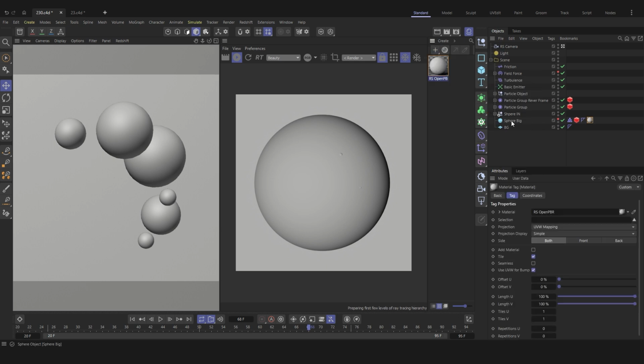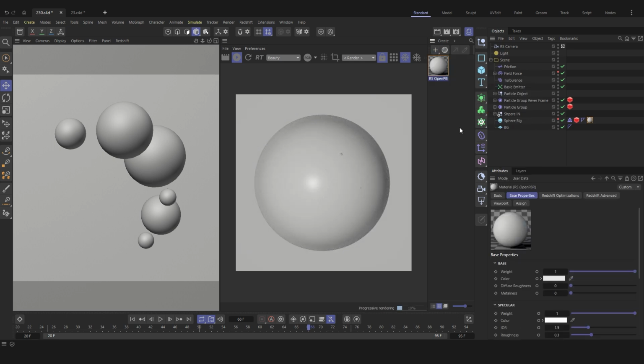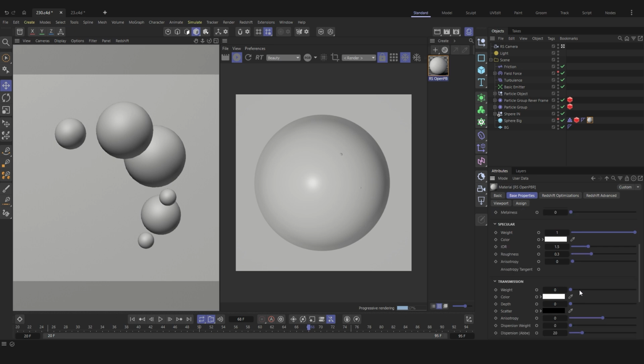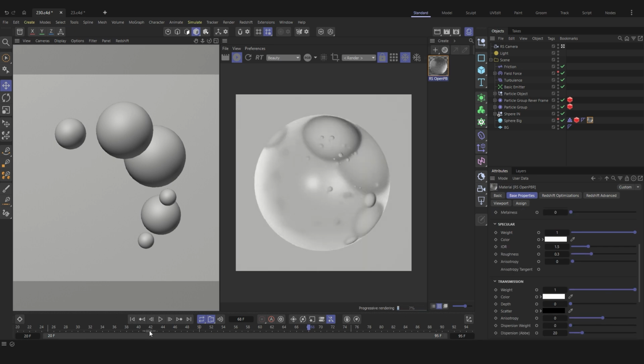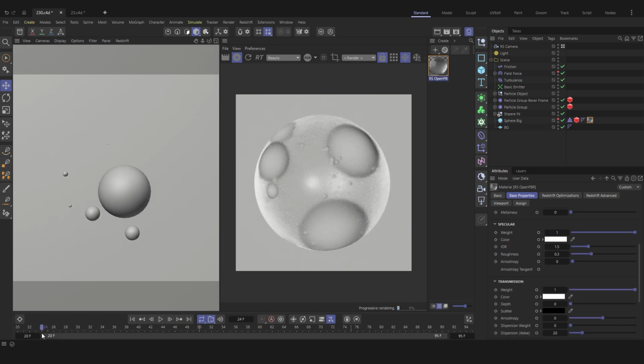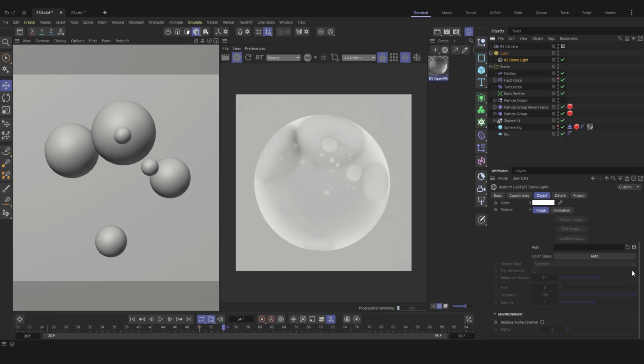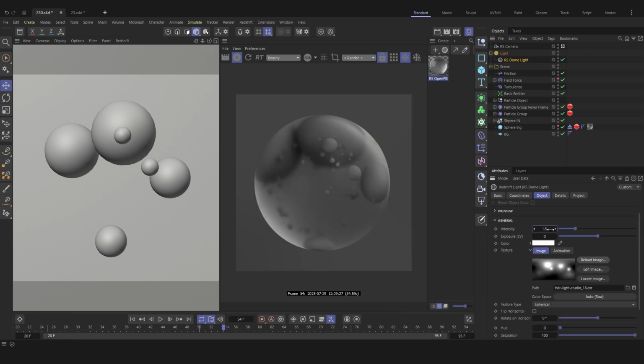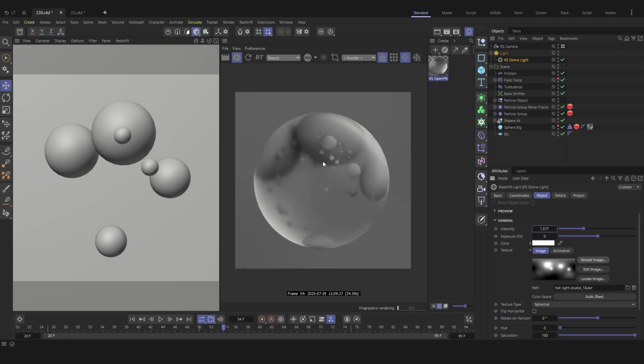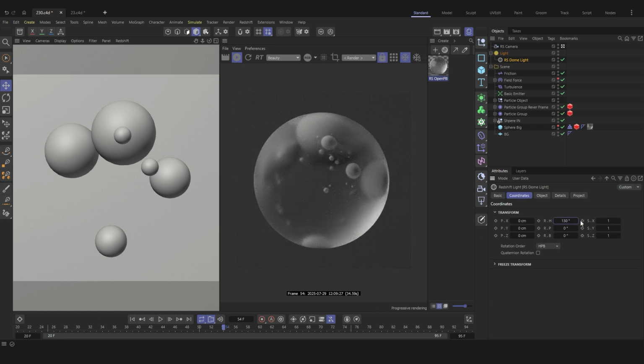Let's start by assigning a simple glass shader to a large sphere so that light sources are reflected in it. Alright, now let's add our first HDR. Drag it into the light folder and use it as the main lighting source. We'll slightly increase the intensity and adjust the rotation to get better reflections. By adjusting the rotation of the HDR, you control where the highlights appear.